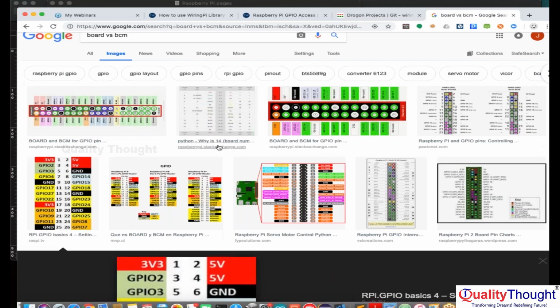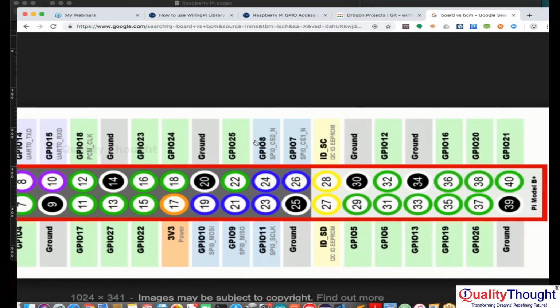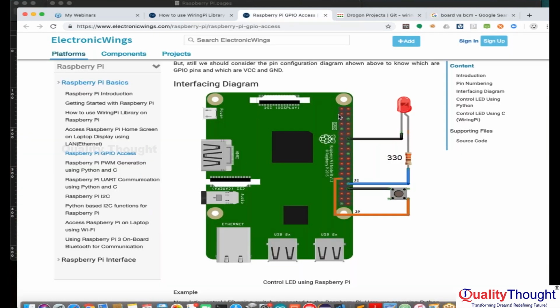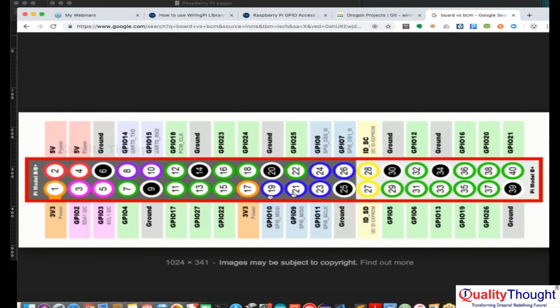Okay. Do you see this? What's happening here? This is a 40 pin header, which you see as part of your Raspberry Pi. It has been tilted here. The first one is 3.3 volts. Then there is 5 volts and 5 volts, and all the blacks are grounds. You can see all the black colors; all you see are the grounds.